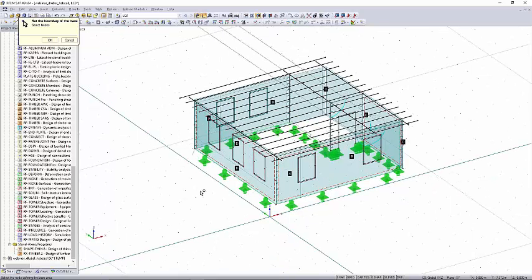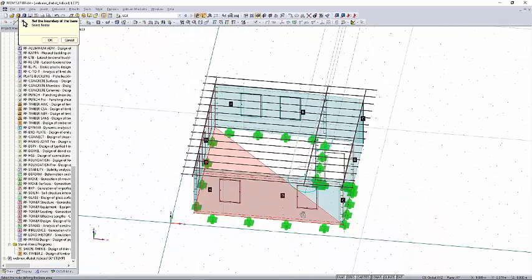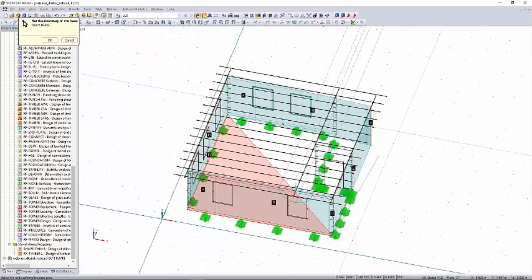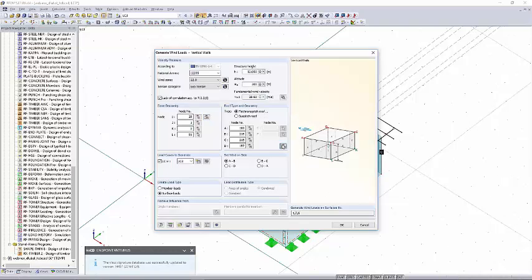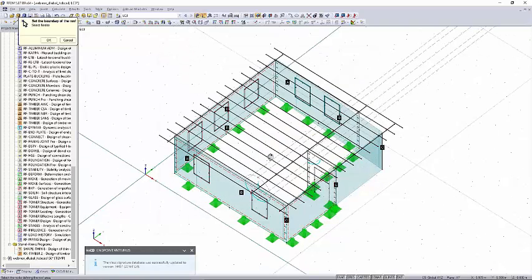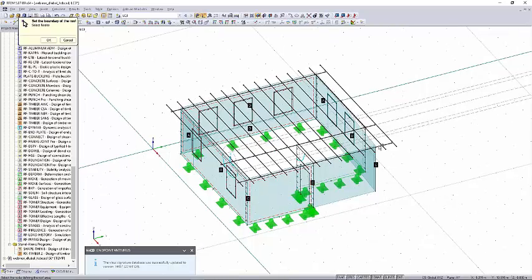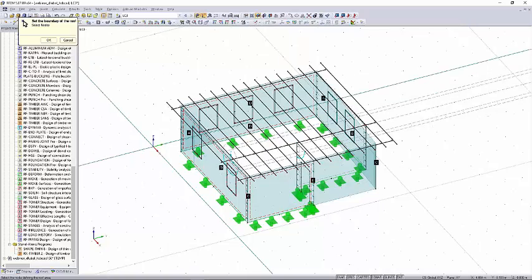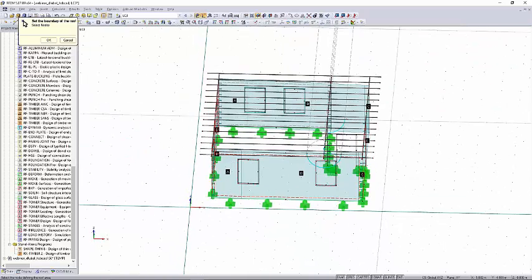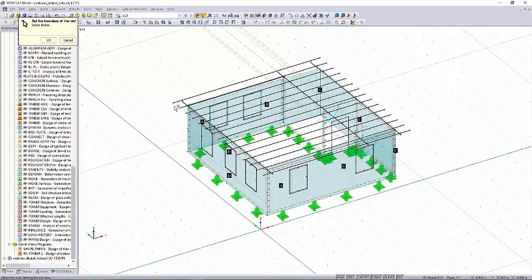So if I start with this edge point here on the bottom, go to this side, and now there's this little post where I also have to interpolate a little bit. This structure is not possible to load with the wind according to the Eurocode, so you have to calculate a little bit on the safe side. That's why I choose this outer node here and not the inner nodes. And then the area I will load is much bigger.